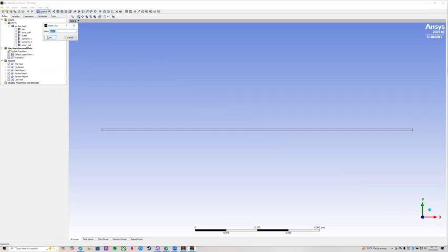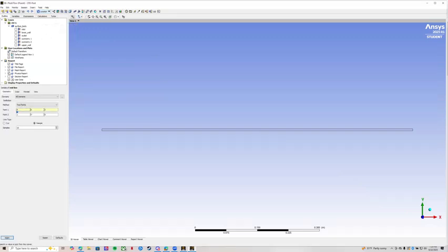Make our line, make a midline. We're going to put that at that 0.375. Same thing down here, 0.375. And put that 0.005 with 100 samples. We apply that, we get our midline again, location and line.